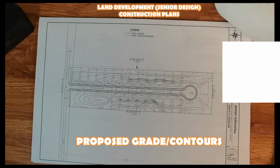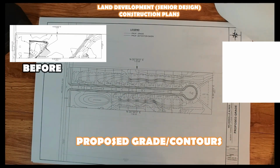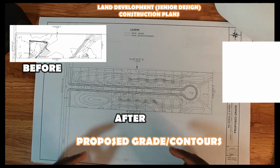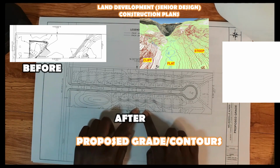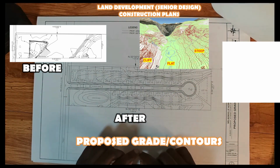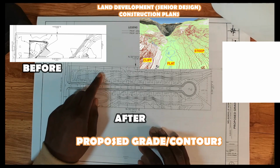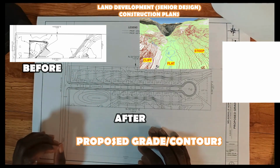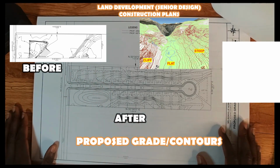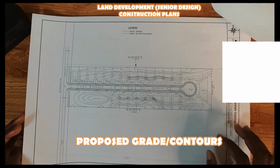So right now what you're looking at is the proposed contours. I fixed what was there before and made it like this. The more squished the lines are together, like in this area, the steeper that particular area is, and the more space there is between the contours, the flatter that area is. So this gives you an idea of what's going on here.